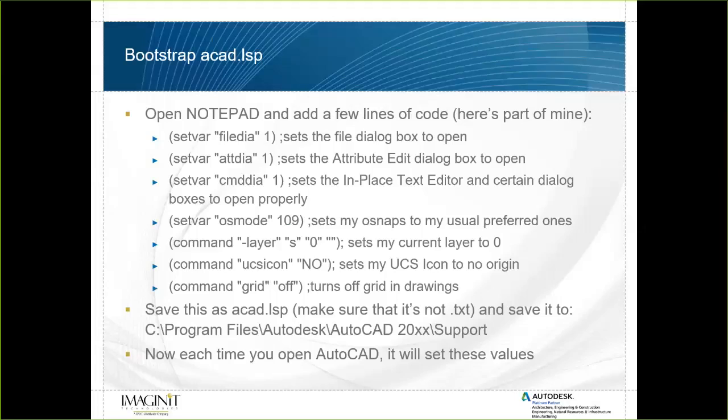Yep, and Frank, you do that all in your acad.doc.lisp. That works too. I usually like the acad.lsp just because then I can set up my system parameters here, and then I can use the ACAD doc to drive another portion of it if I'm loading Lisp routines, things like that.